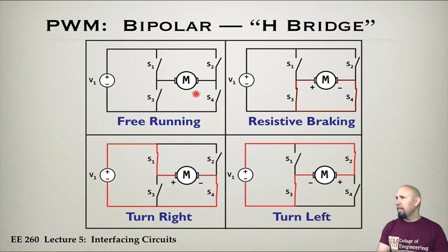So what's going to happen in this case is that this will stop, but it will take a longer time to stop, depending on the inertia of the system and the motor. In this case, when you stop, it actually provides kind of a braking action. So it's not exactly a brake, but it's noticeable. This configuration will stop much faster than this.